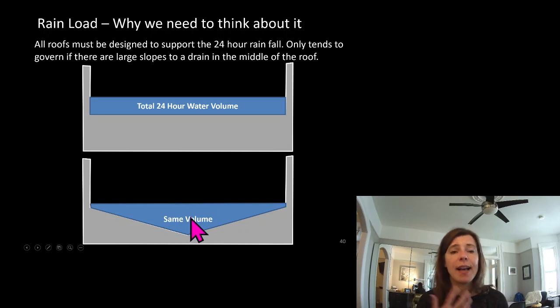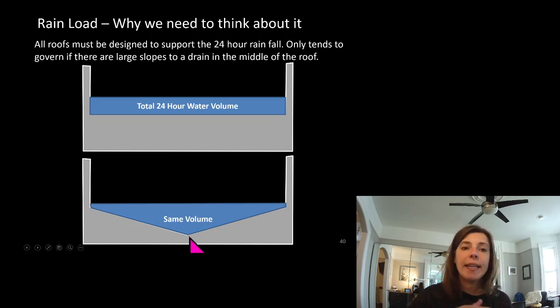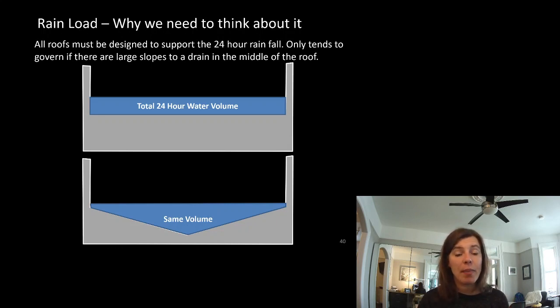In all the projects I've done, I'd say 3 or 4 projects have had 4 or 5 beams governed by the rainfall event. Had to check it, had to think about it, had to do a quick study on it, and that's where I needed to communicate with the architect, because I needed to know where the drains are and what your slopes are. So I needed that layout of drain patterns, and very early on, the architect needed to think about what type of drains we are using. Do we have scuppers? Where are they going to be, at least roughly, so that we could do a design exercise to find out if there's any elements governed by the rainfall, which there wouldn't normally be because our snow would govern.